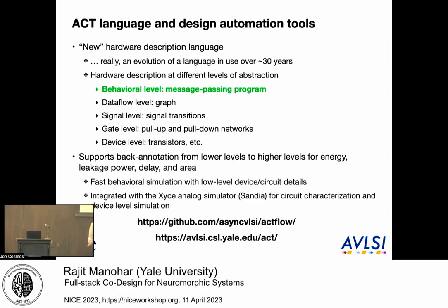What's more useful is you can take characterized results from a very low level of abstraction, like SPICE simulations of your circuits, and back annotate all the way up to the behavioral level. Then you can run your models at that level of abstraction and get all the metrics you care about. For the lowest level, we've integrated our simulation framework with Xyce. So we use the SPICE simulation from Sandia, and these are all open source tools. They're freely available. You can download them. So this flow is up and running. We've taped out about half a dozen chips with this flow. They work, okay? And this flow is an evolution of the tools that we used to design both TrueNorth and the BrainDrop chip, and to start a company and a bunch of other things. They've been used for a while.